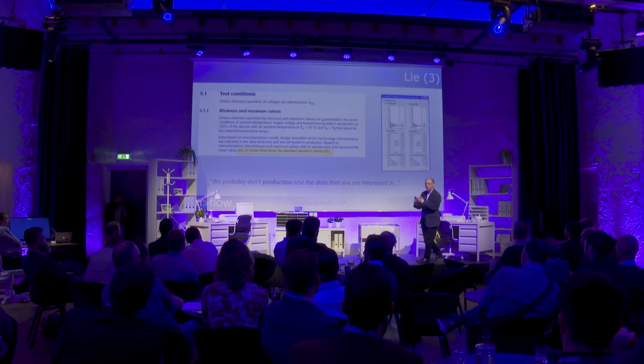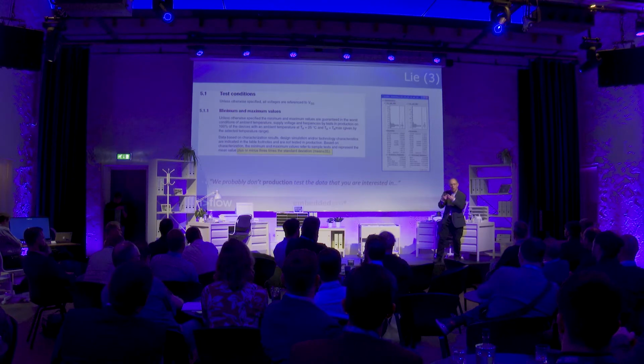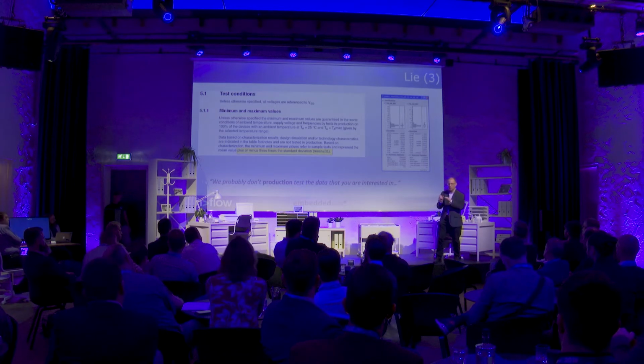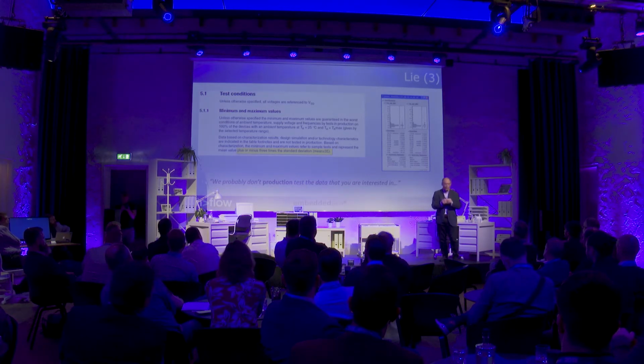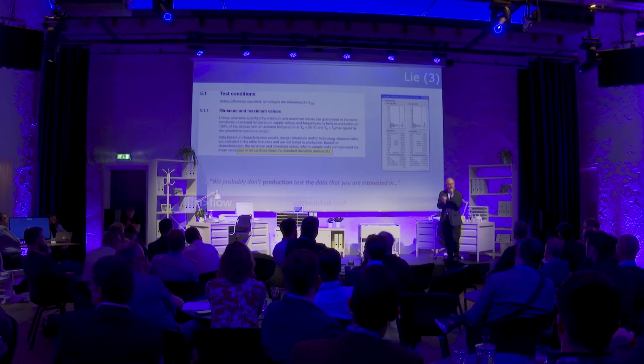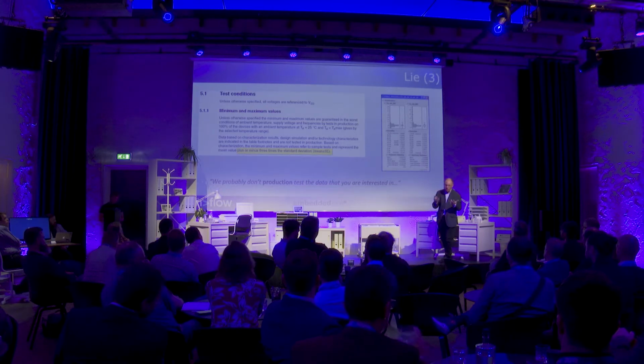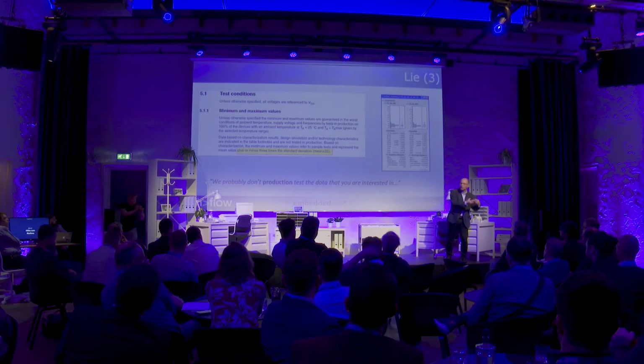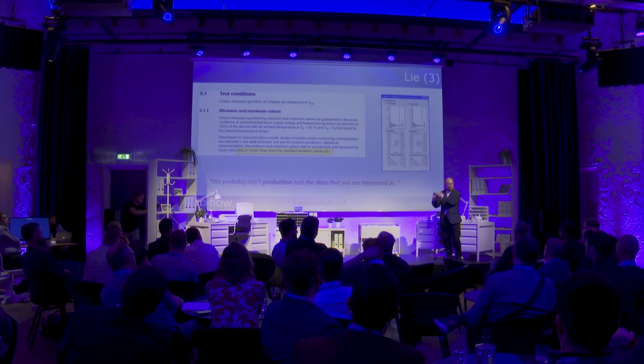What does characterized mean? It means the very first wafer that came off the fab when it was being hand optimized, and your physicist is optimizing the process day by day as that first ever wafer is grown with no optimization for yield and don't care about how much yield I get from my wafer. That precious, very carefully brought up little infant is the one that will be used to characterize the sleep mode currents. So what's published in the data sheet was true for that first ever wafer. It may not be true for what you buy from EBV for your product.